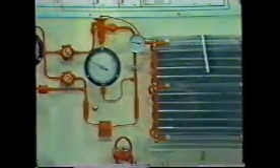The evaporator consists of tubes in parallel circuits, commonly called a coil. The vertical parts across the coil are extensions called fins. These fins increase the coil's surface area to permit greater heat transfer. Air may be blown over the coil and fins to maximize airflow and increase heat transfer. The refrigerant flows inside the evaporator coil. It enters the coil through the metering device. In this system, the metering device is an expansion valve, but other types of metering devices can also be used. We'll talk more about some of these later on.